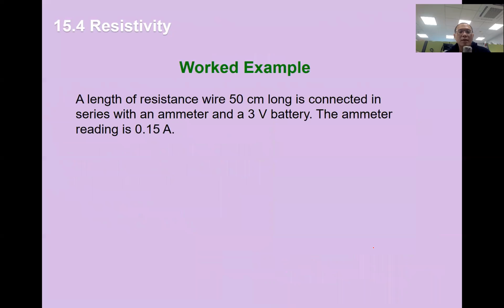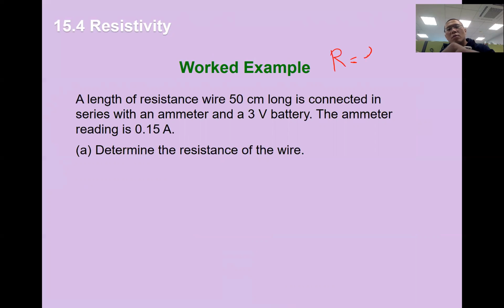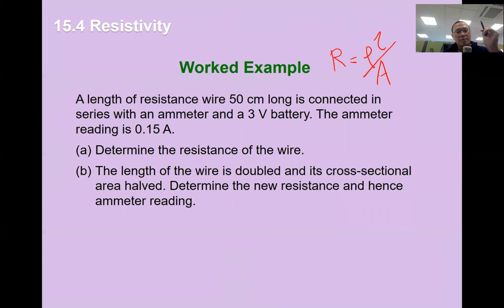Now, common questions that we look at mathematically revolve around the formula R equals rho L over A, the resistivity formula. We make use of this formula to solve questions mathematically, and we can use it to decide how long or how thick a cable I want, or even what type of material I want, because the amount of resistance I want in a circuit is limited, or predetermined, based on my needs for the circuit itself.